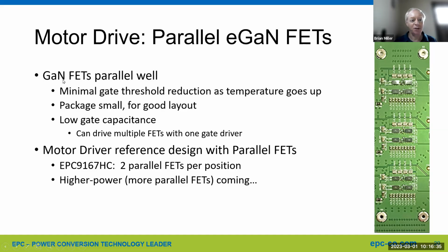But the GaN FETs actually do parallel very well. As temperature goes up, the gate threshold doesn't decrease very much at all. With MOSFETs, that can be a problem. You can have the hottest FET turn on first and turn off last, so it gets even hotter. So you can have the hottest FET get even hotter, and that can cause some problems. That's minimized with GaN FETs. Also, the package is very small for good layout.